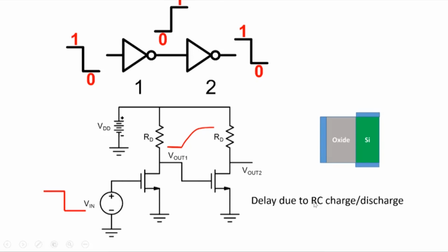So all my circuits, all my complicated, let's say adders, subtractors, microprocessors, all of them have delays in them. There's a certain speed at which they work. And the fundamental reason there is a speed limit to all of this is basically because of capacitance charging and discharging. So the speed of the circuits is eventually limited by your RC circuit, a capacitor charging and discharging.